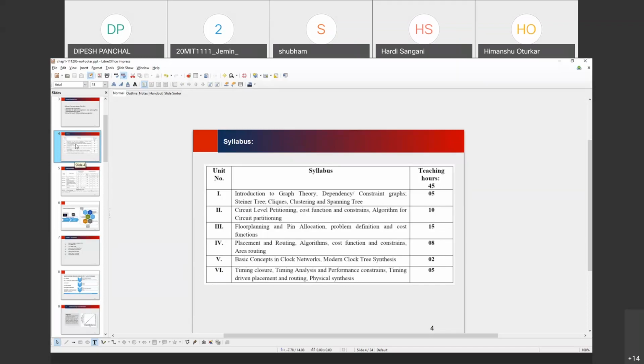We need which type of gate, so that information is also there. Okay. That means a wire also varies with respect to gate. If the gate is very far away, the connection requires a long wire. If it is shorter, nearer to each other, it requires a shorter wire. Okay, sir. There is a link A to B, but you have to define it in the proper way in the netlist.